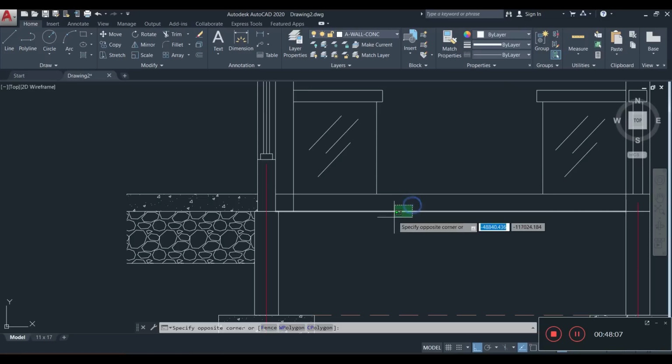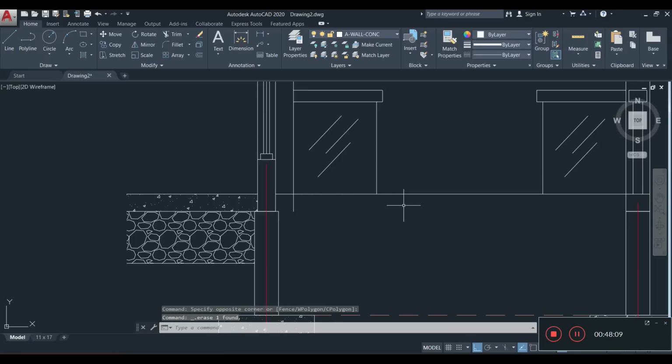Now considering that I'm saying this is the floor level, this is normally a thin layer of whatever material it is. I'm going to assume that material is probably about an inch thick, so what I'll do, I'll offset down 25.